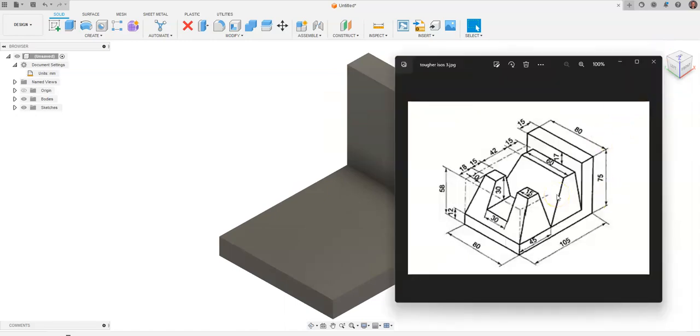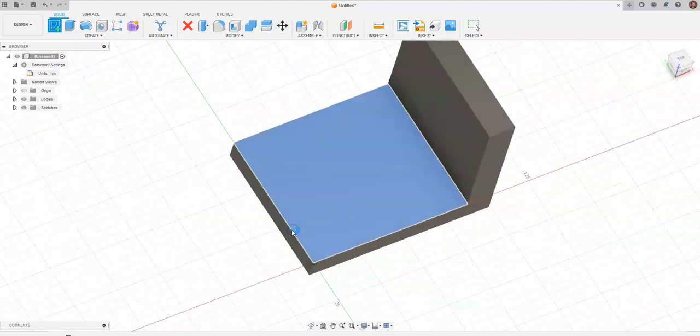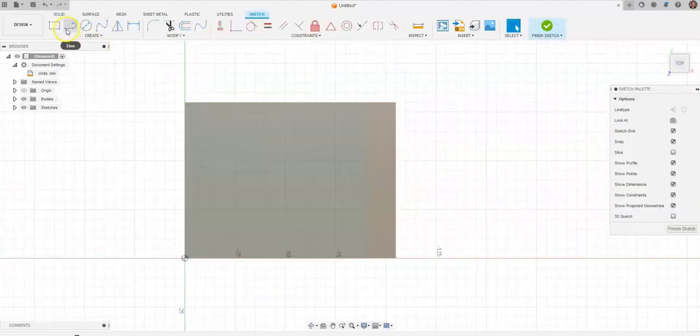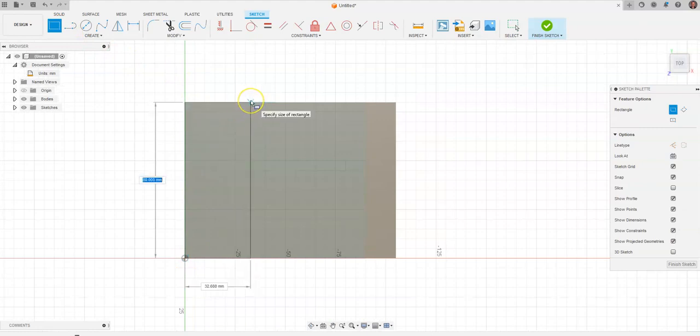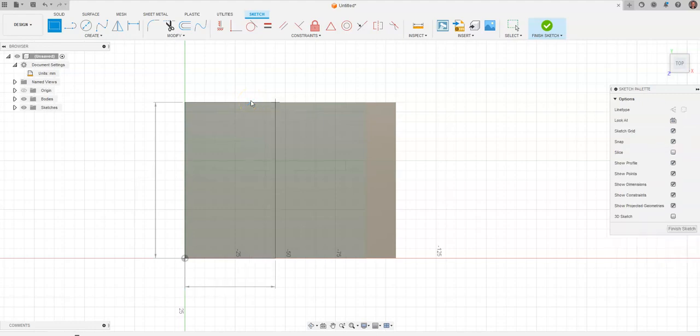Now what we need to do next is start creating these surfaces that we need to create these lofted views. And this line right here is 45. I know it's the full depth because I can see it go the full depth back here. So we'll grab a hold of Create 2D Sketch. We're going to click on this surface. I'm going to grab a hold of 2-point rectangle. When I drag up along the line, automatically it's going to snap to 80. I'm going to hit Tab, go to 45, and hit Enter.